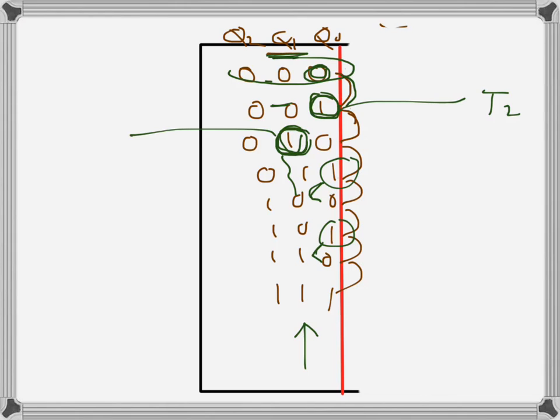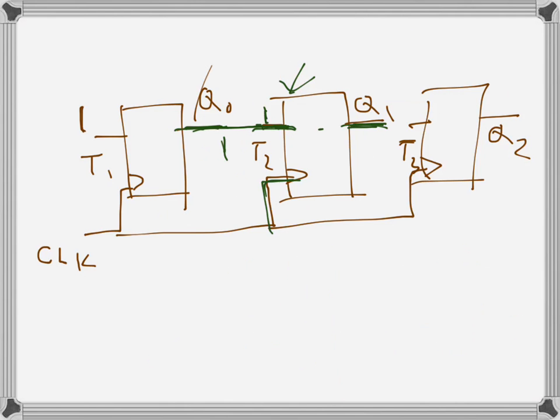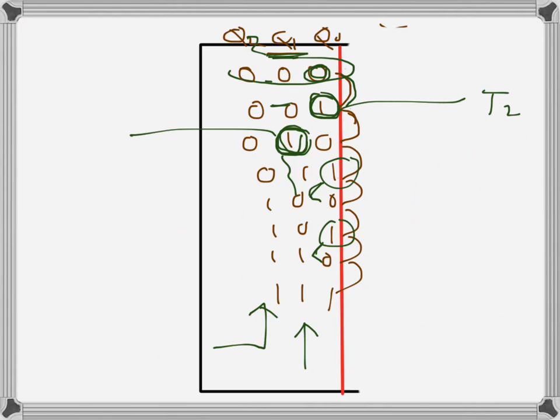Now if we think of the most significant bit, that is the leftmost column here, Q2, we are trying to figure out what input it will have. It is getting the clock, but the output should change. When does it change? Let's look here. It's changing here, and that's the only point it's changing. Again, it's changing here when it has counted up to 111, so up to 7.